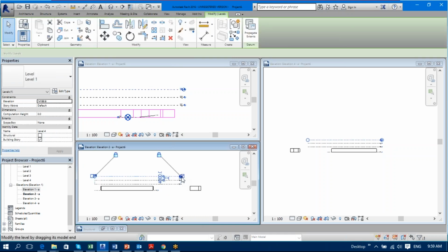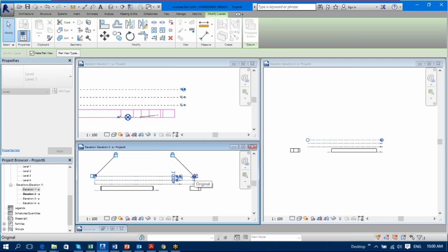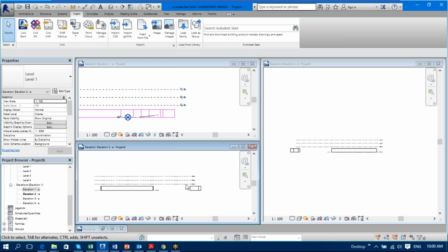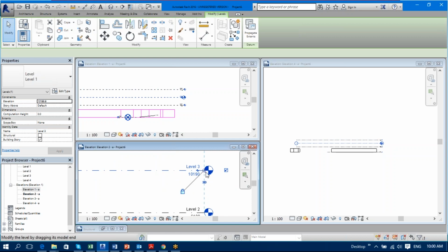now I can't see from this zoom out what I am going to select. So I am using my tab key and my status bar to know what I am going to select. If I select here, I would end up creating an elbow. So I will say tab, tab, tab, tab, tab. Now this is the right thing. Now if I select here, you see what happened? That thing came.